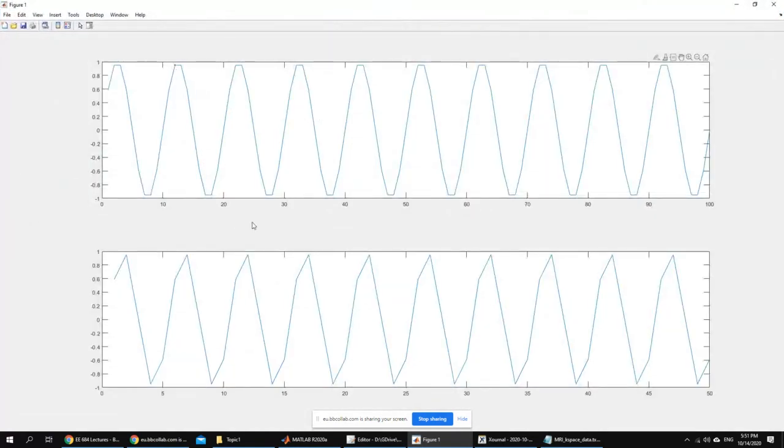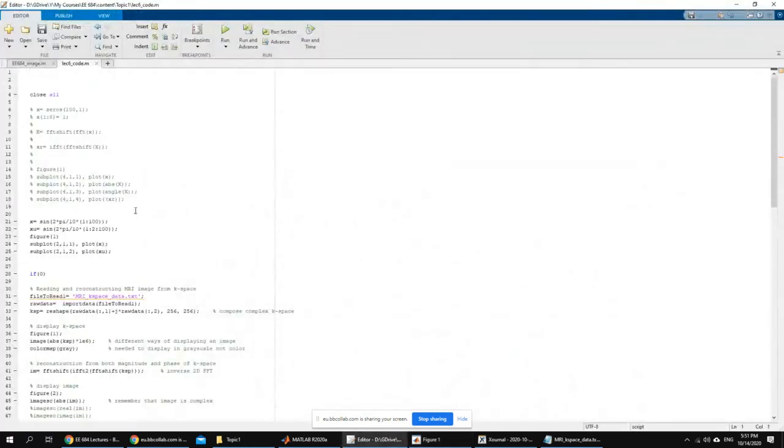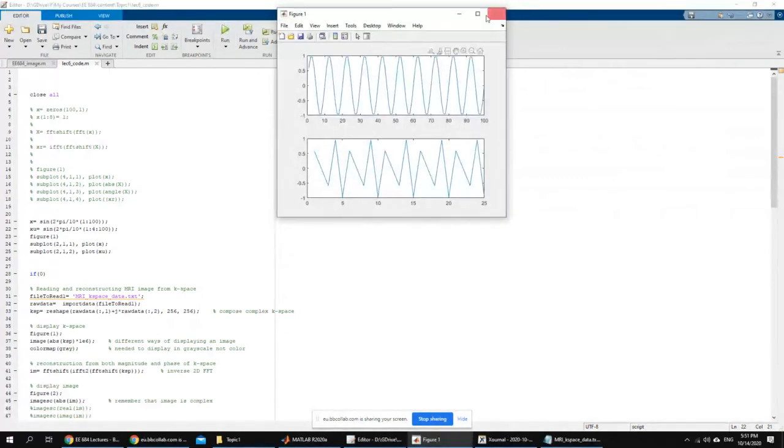See now, first of all, the number of samples in the undersampled signal became 50. The sampling of the sinusoidal signal doesn't really look right. It doesn't look as good as this one here. We can undersample a little bit further so that we can see that effect. If I, for example, undersample by a factor of 4, now I'm taking one sample every 4 samples. Let's see what comes out. How do you like that?